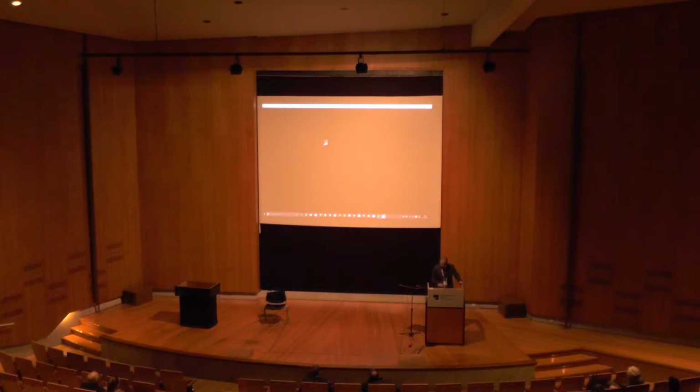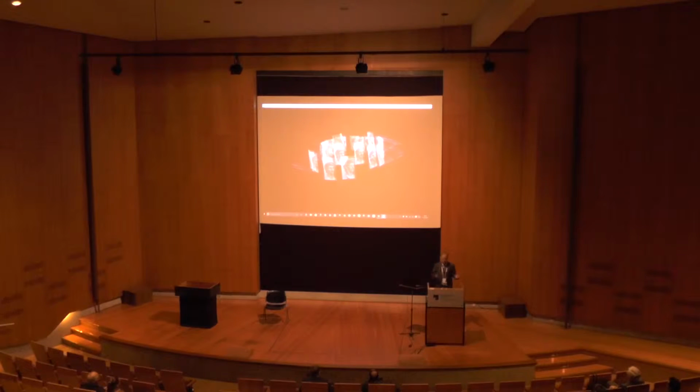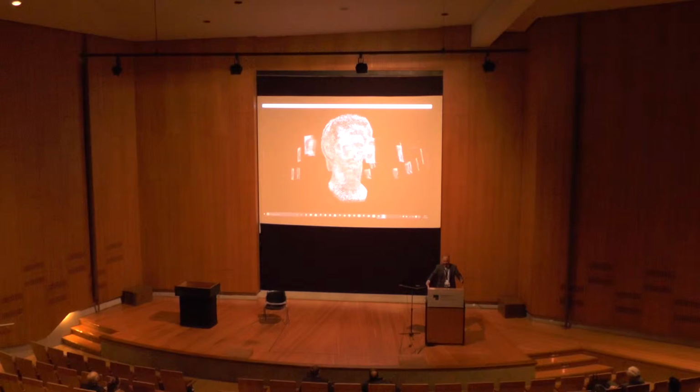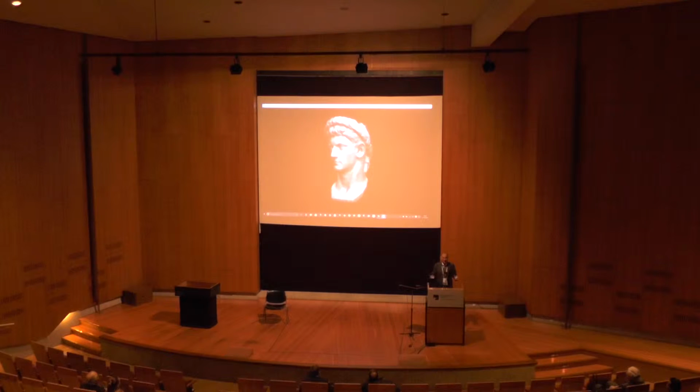And you see here an example of how it works. We first of all take the photos, so everybody can do it using their smartphone camera. Then you use photogrammetric software like Visual SFM whatsoever. You get already a coarse point cloud, and then if we feed all the orientations and the locations of the photos into a dense image matcher, we get a very dense point cloud. You see it now. Then you can make a watertight model. You can triangulate all those points, and then finally you can put the real texture on it, and in this way every one of us can contribute to a 3D reconstruction just using your smartphone, which you always have in your pocket, if you use the right software.